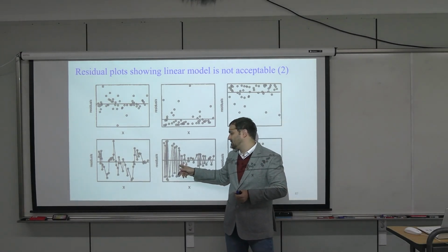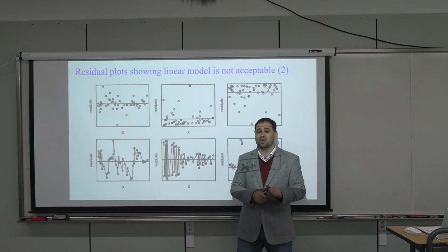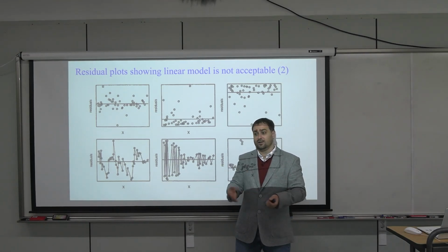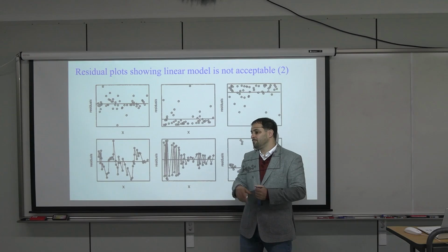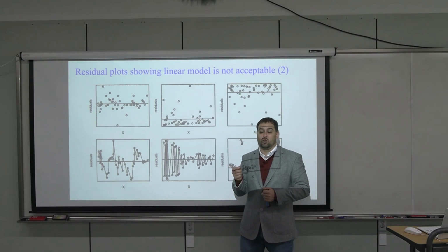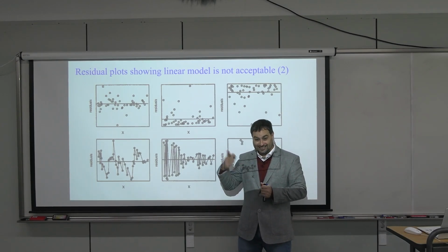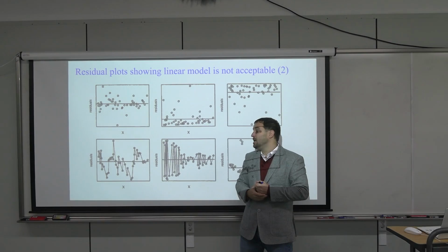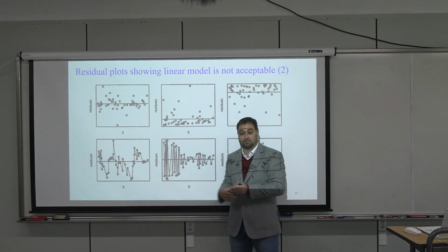I've encountered this because I use what are called system thermal hydraulic codes. Basically, they use finite differencing to solve for fluid flow and heat transfer in piping systems, when you have heat sources and heat sinks. There, you can have numerical instabilities in things like finite differencing and the finite element method. You're discretizing a continuous process, and some of your finite differencing methods are unstable, especially if you're taking large time steps.